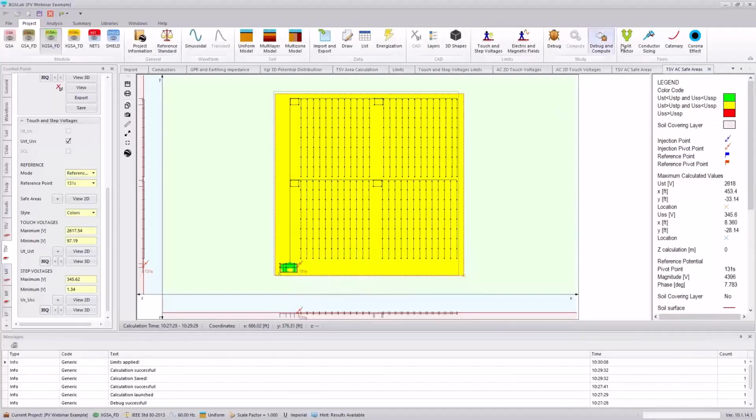But a thing to know if you're using a tool that doesn't account for that voltage drop is that you can actually artificially see positive results, meaning you could see green areas in areas that are really non-compliant, or you could see artificially negative results, meaning it could look like it's failing, but in reality, when you account for that voltage drop, your system looks compliant.